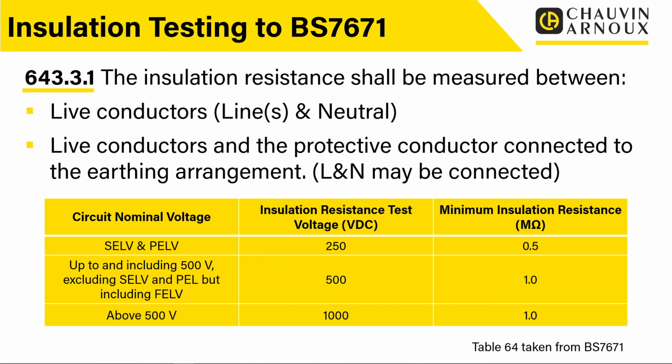And it says the insulation resistance shall be measured between live conductors. So I'm measuring between live conductors. And I think certainly people who've been around a while, like I have, remember the term live being used for the line conductor. So we had the live conductor, then we started calling it the phase conductor, and then now we call it the line conductor.